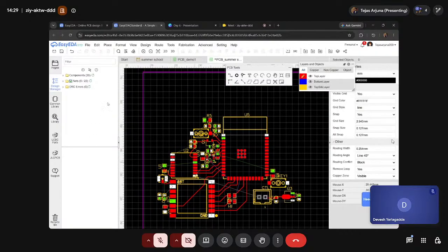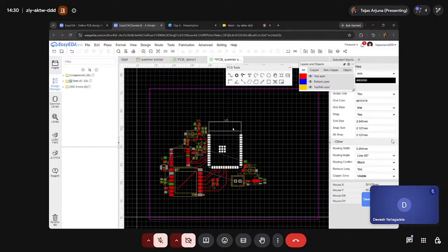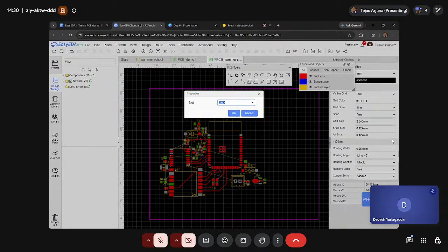And the second reason is, having a plane does not reduce your loop area. It still has to go through all these signals, travel all here and go here. And if you keep the plane here, it has so many obstacles, and the loop area still is high, and inductance increases, impedance also increases, the radiation also is high. So we don't want those things. This is a GPS module, and LoRa also, those are highly sensitive. I don't want any noise in my circuit. So I'll go with 2 more layers. Go to the inner one, place the ground pour, a copper pour with net ground.